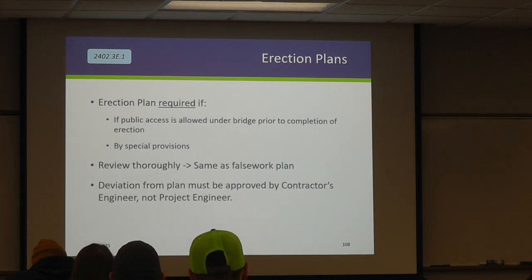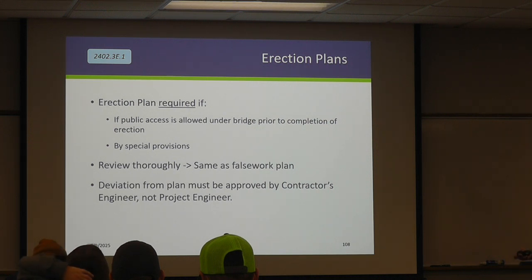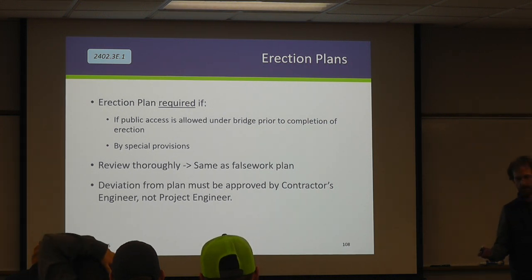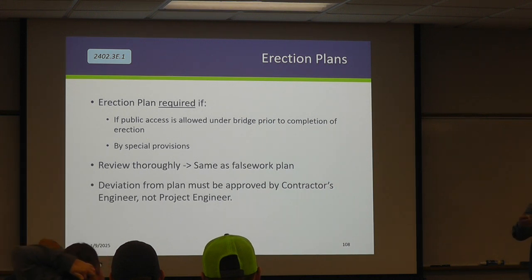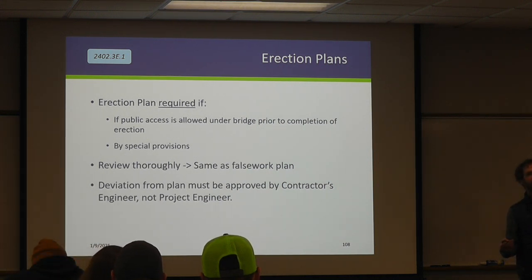they want to do. So erection plans are going to be required if there's any sort of public access allowed under the bridge when it's not in its completed state, because we haven't analyzed that yet. So think about, let's say you're building something over I-94, right? And you only have a 12-hour closure period, so you're going to get so much of the work done, then you have to open it back up to traffic until you can work again the next night. That would be an example of when you have to have an erection plan.